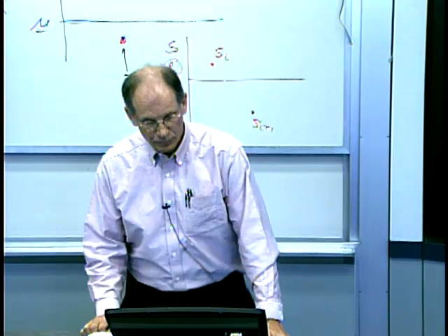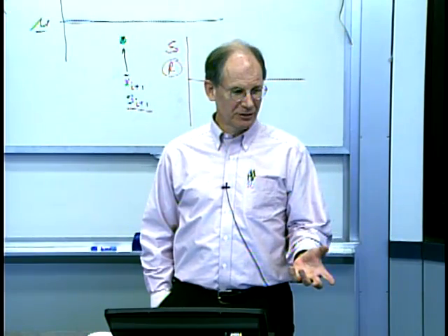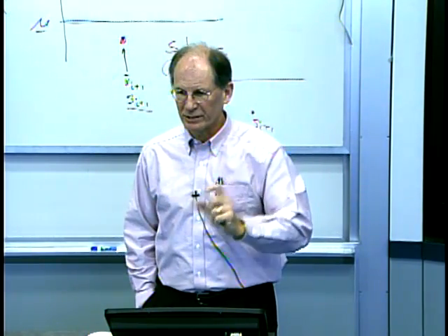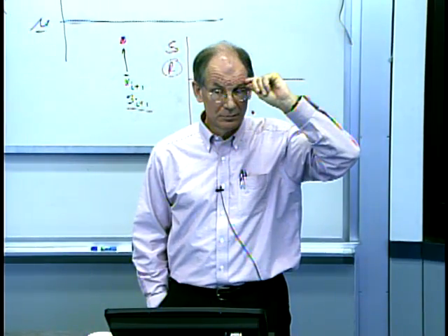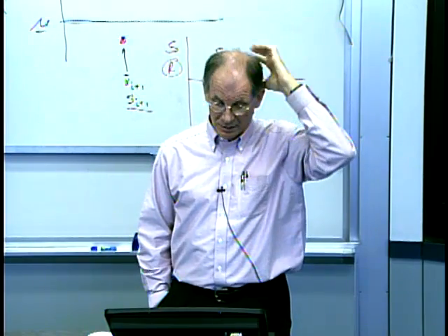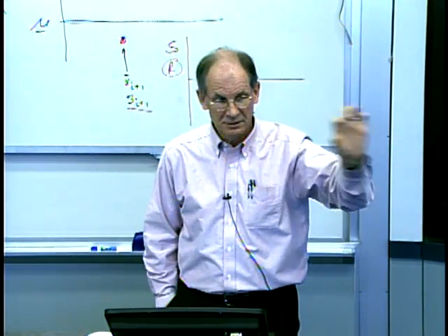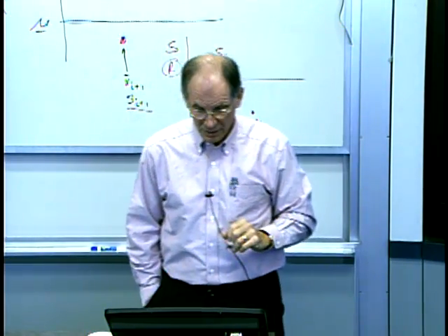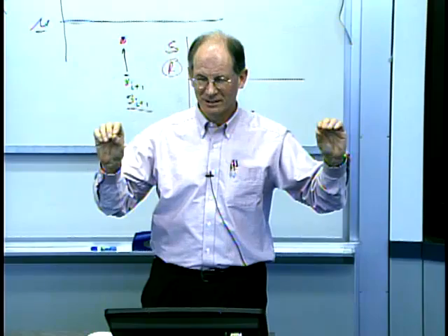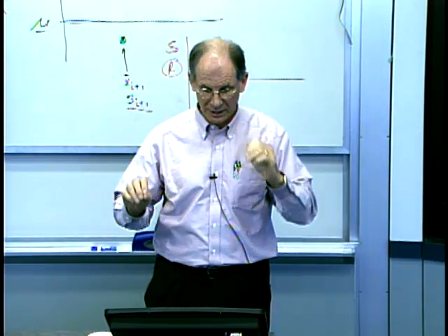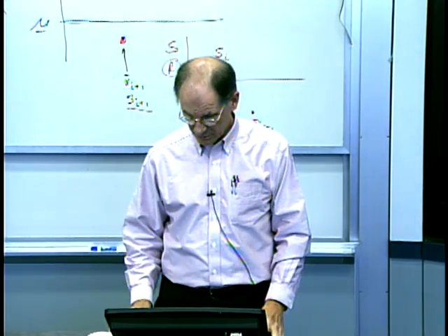Improbable points. Now, they've quantified this by saying, look, if I look at any triad of points, if 2 of 3 of those are in the plus or minus 2 sigma band, that's pretty improbable based on confidence intervals. 4 out of 5 outside the plus or minus 1 band, that's pretty improbable. Or all the data inside the plus or minus 1 band. That shouldn't happen either if my process is stationary. Okay? So each of these things could indicate that it's not following the expected normal behavior.